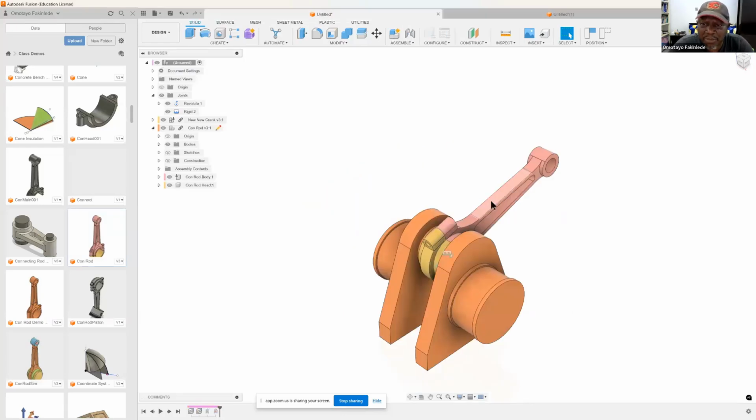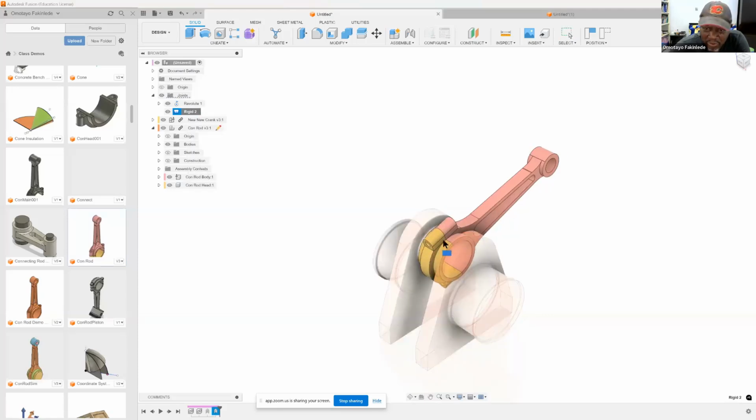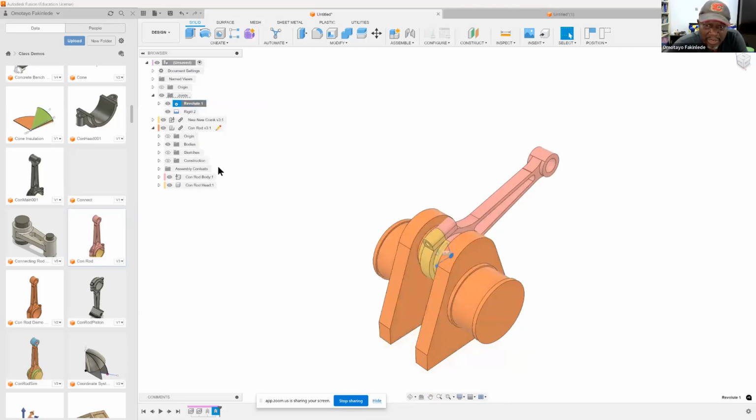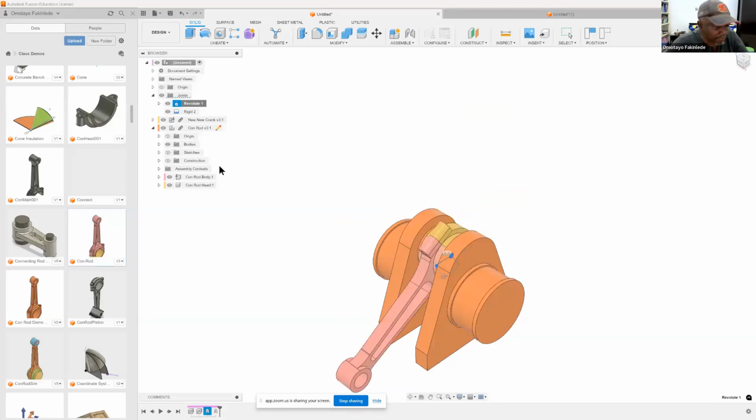Okay, this is directly now on Fusion 360, and we have decided that we can test this rigid joint and animated joint. You can see the rigid joint between those two shows you that they are bonded together. If we animate the revolute joint as we have just done, we can animate the joint relationship. You can see that everything is working fine.